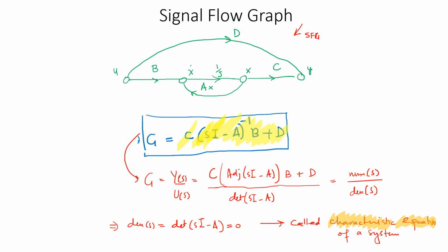And what is that? Let's try to explore that. Let's do one little exercise to further strengthen the understanding. So in this particular example, I'm going to make use of a spring mass damper system, but I'm going to start from a block diagram so that the process that we have just explained in the graphical paradigm is well understood. So I'm going to have the input provided to it as force, which is then multiplied with this block of 1 over m.